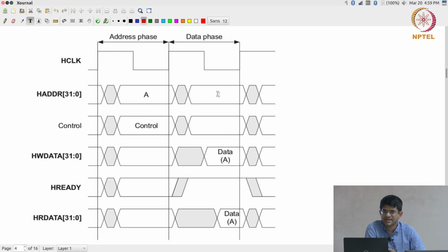So now let us start looking at what a bus transaction looks like. As far as the bus transaction is concerned, we need to essentially look at a lot of these timing diagrams. These timing diagrams are going to be common throughout the rest of this presentation. You can figure out what is going on over here. Essentially you have a clock signal right on top, which is just a square wave, as you can see over here. As the square wave goes through its cycles, we have these vertical lines that indicate cycle boundaries.